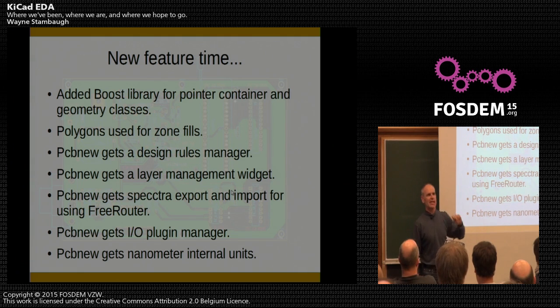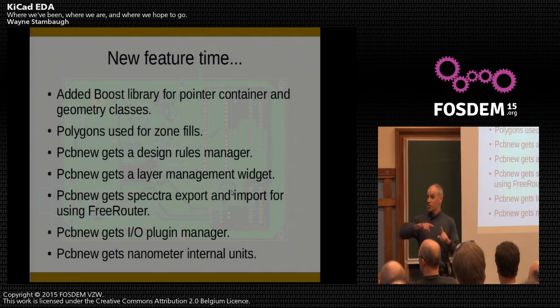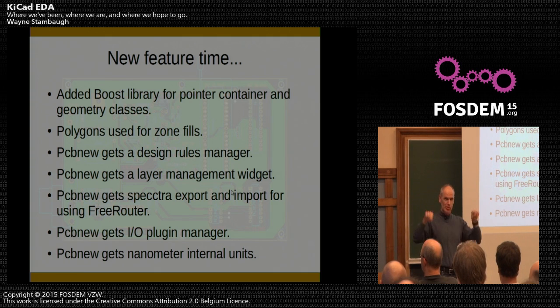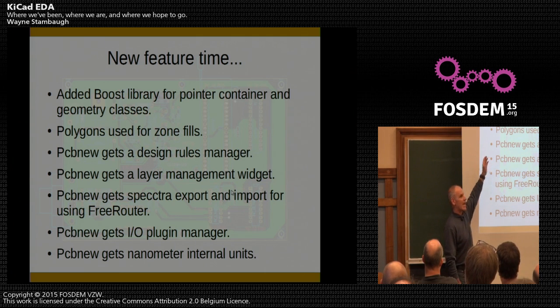Originally, the zone filling algorithm, I don't know how many people used it that long ago, used segments. So literally you would do a zone and it would fill with little teeny tiny segments. And if you ever had a board made, if you weren't careful, you looked at the end, you saw a bunch of little humps, where the butt end of the segment was drawing in the Gerber output file. So that changed. We went from the segment fill to the polygon fill.